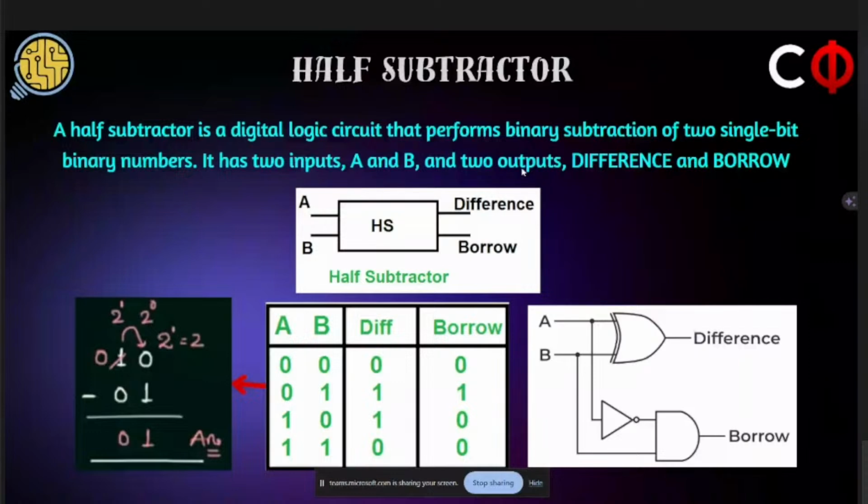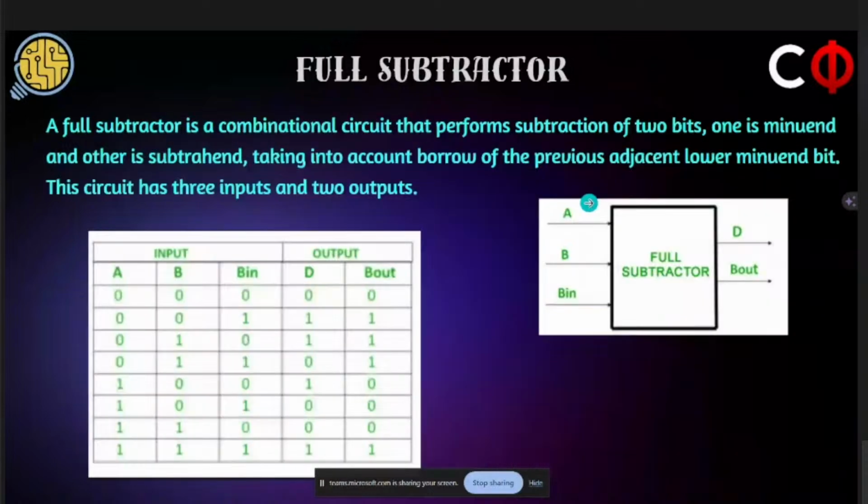Full subtractor is very similar to full adder. And this is the truth table for full subtractor. You have 3 inputs and 2 outputs, same as in the case of full adder. Here A is called the minuend and B is called the subtrahend. And you get the outputs as difference and output borrow.